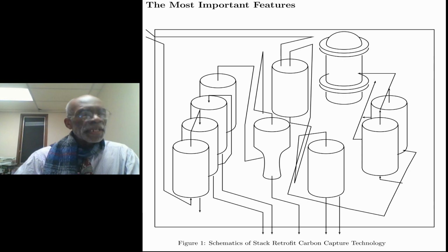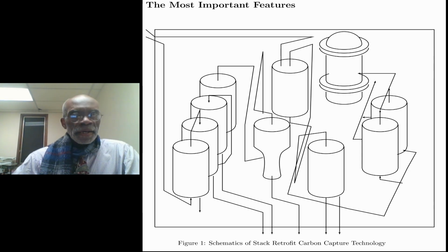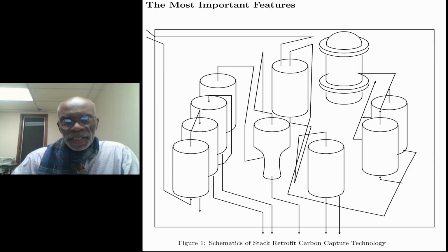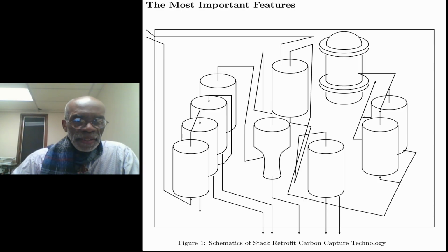The metal dust aggregator is designed with the company's ion separator and is effective at removing the metal particles. The slag is collected at the bottom of the cyclone separator while the rest of the gas exits at the top. The top outlet of the cyclone then flows into the acid scrubber.